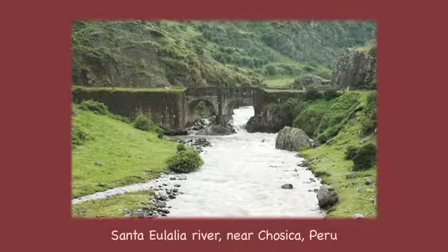Maximum catchment relief is the elevation difference between the highest point on the catchment divide and the lowest point at the catchment outlet. The principal watercourse is usually the longest watercourse and the one conveying the flow to the outlet. Relief ratio is the ratio between maximum catchment relief and the longest horizontal distance measured along the principal watercourse. The relief ratio is a measure of the intensity of erosional processes, or geodynamics.